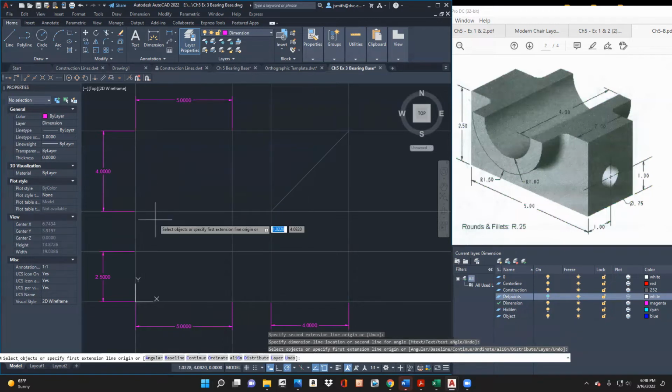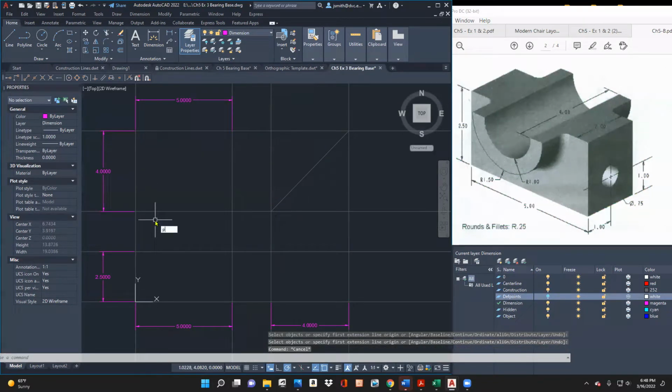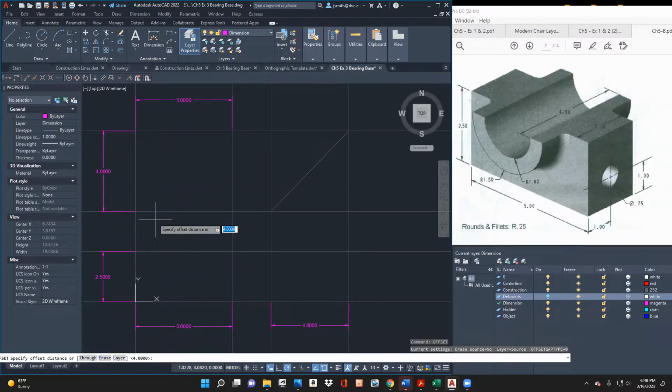And let's go to our, we're going to be working, I think actually, let me just double check here. I don't think I need it on the offset, need to have that layer selected, but let's see what happens here. So what I'm doing is I'm going to build that half circle. Let's just, for my sanity, put that halfway in between. Because it doesn't tell us, we have to assume that's symmetrical. So that means that it would be 2.5 inches from either side. So I'll type in 2.5, enter, select the object, and there we go. And so let's just verify that real quick here.